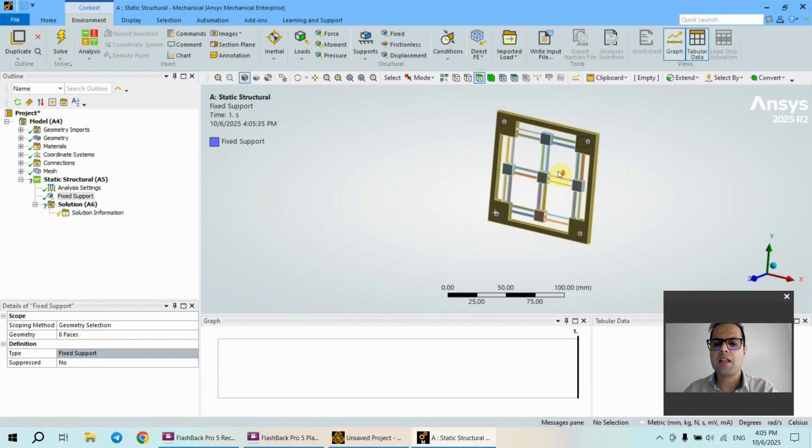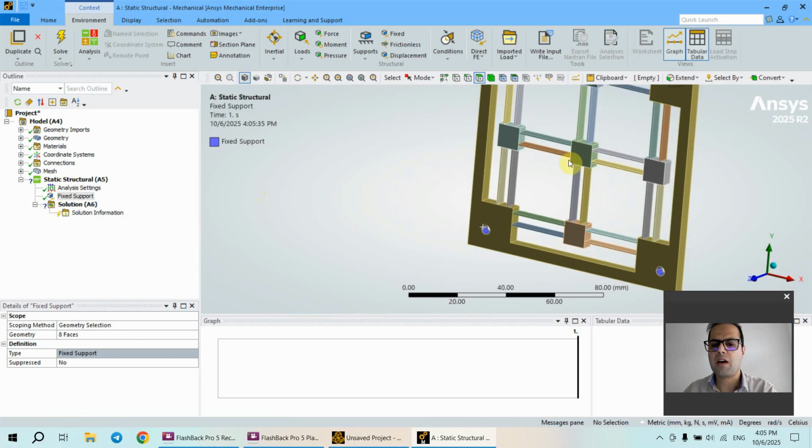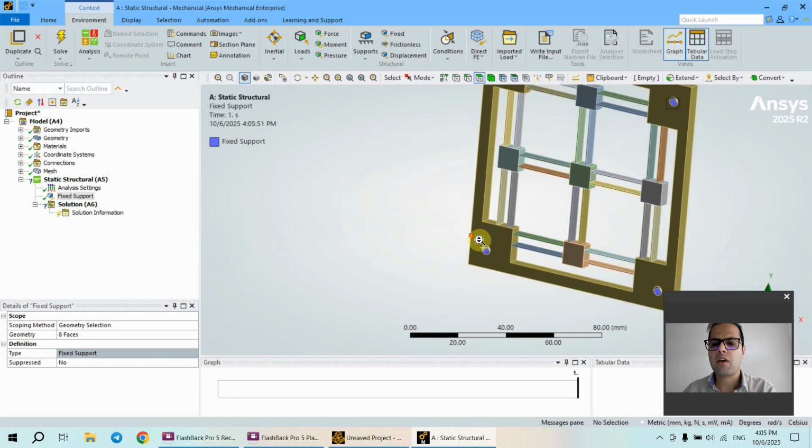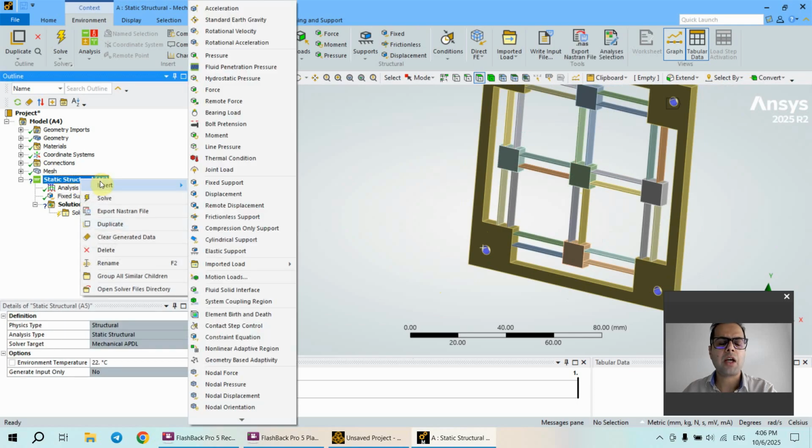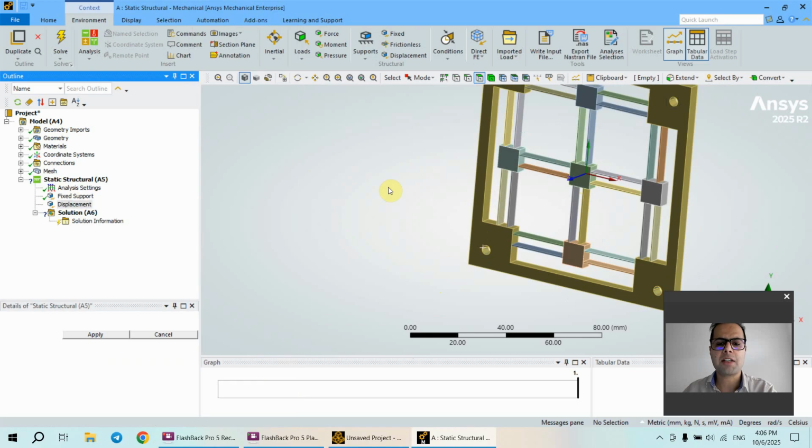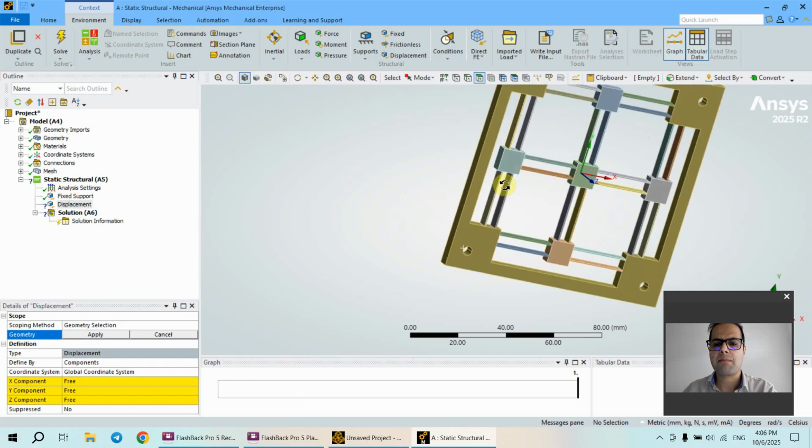The idea of such a flexure is to have fine and accurate motions in X and Y directions independently via these 4 blocks. Therefore, the metrology object that is attached to the central block is supposed to move the exact amount that either of these 4 blocks move. Therefore, we could apply displacement boundary conditions, for example, to this area.